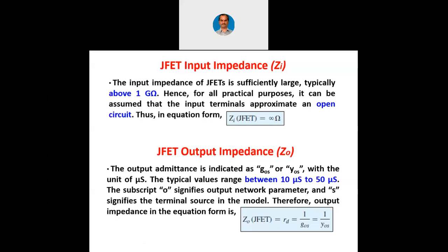So at the last stage when we have an amplifier, the very last stage is supposed to be a power amplifier based on the application. Now when we connect a very low impedance speaker, it is going to consume a very large power. So naturally there the output impedance of the amplifier must be ideally 0 or very less. For example, if you are connecting a 4 ohm speaker as the load, the output impedance of the amplifier is supposed to be 4 ohms, because that 4 ohms and 4 ohms will match with each other and that is when maximum power will get transferred.